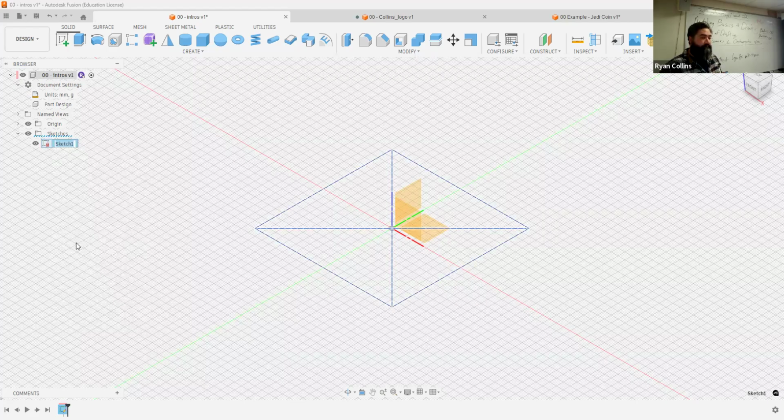What's up? How did you make it show the construction line? Double click on the outline of the box and press X on your keyboard.